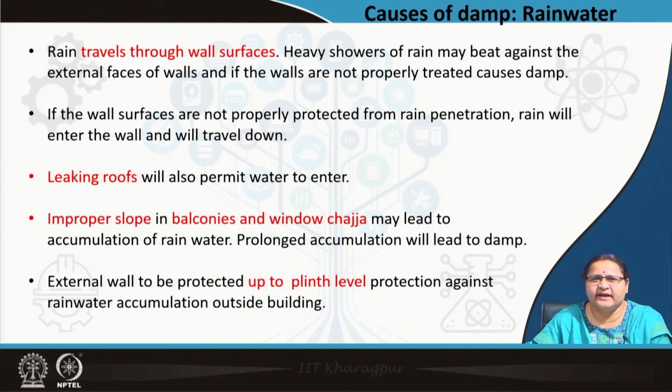So, you need to protect the external wall by application of proper paints, and allow the water to travel down. Now, this water may be trapped on the roofs if there is not proper drainage at the roof. So, these may lead to leakage from the roof. Rainwater, if it is trapped in the roof for a long time, may gradually damage the rooftop, that is the topmost ceiling, and you will see it as damp when it has already percolated inside.